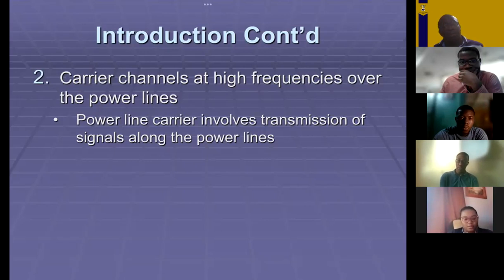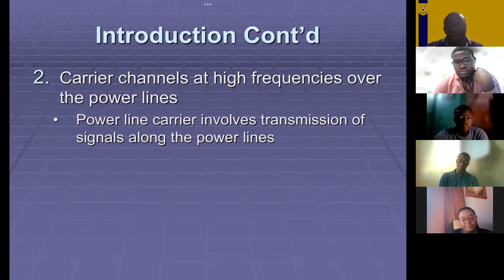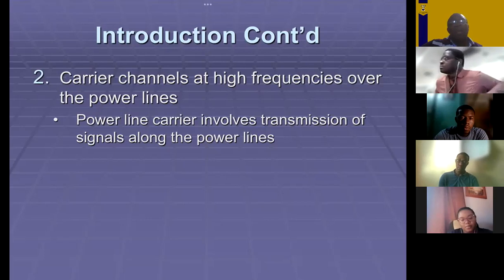Protecting feeders. We're protecting lines. Yeah. Now, for the power line carrier, if I'm protecting a power line, it means the possibility exists for me trying to communicate on the affected line. You with me? It's because I'm superimposing the signal on the line.